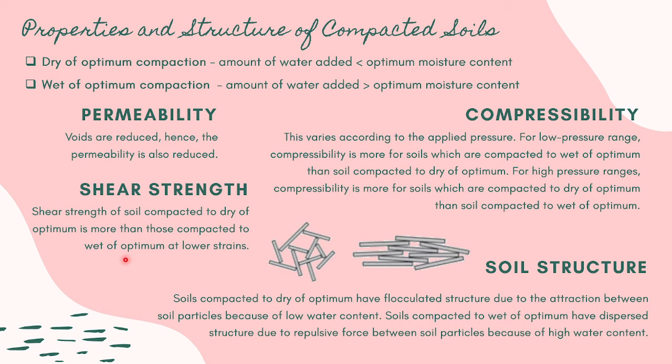Next, we have the shear strength. The shear strength of soil compacted to dry of optimum is more than those which are compacted to wet of optimum at lower strains. Next, we have the soil structure.